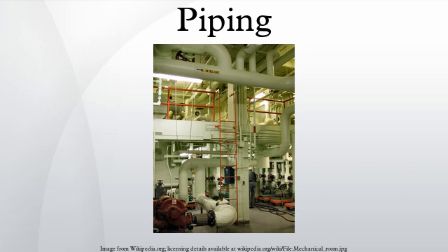It is necessary to evaluate the mechanical behavior of the piping under regular loads as well as under occasional and intermittent loading cases such as earthquake, high wind or special vibration, and water hammer. This evaluation is usually performed with the assistance of a specialized pipe stress analysis computer program such as Caesar. In cryogenic pipe supports, most steel becomes more brittle as the temperature decreases from normal operating conditions, so it is necessary to know the temperature distribution for cryogenic conditions. Steel structures will have areas of high stress that may be caused by sharp corners in the design, or inclusions in the material.